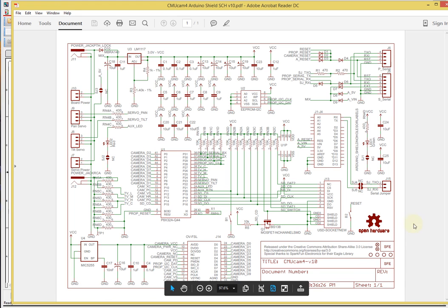and it shows you one of the biggest problems that I have with many of the so-called open hardware schematics that I see put out there, probably because of inexperience, and that is what I call a fragmented design. Basically what we have is nothing but schematic pages with symbols just pasted on them. I look at this and I cannot tell what the general flow of the signals in the design is, and I cannot see immediately what is connected to what.